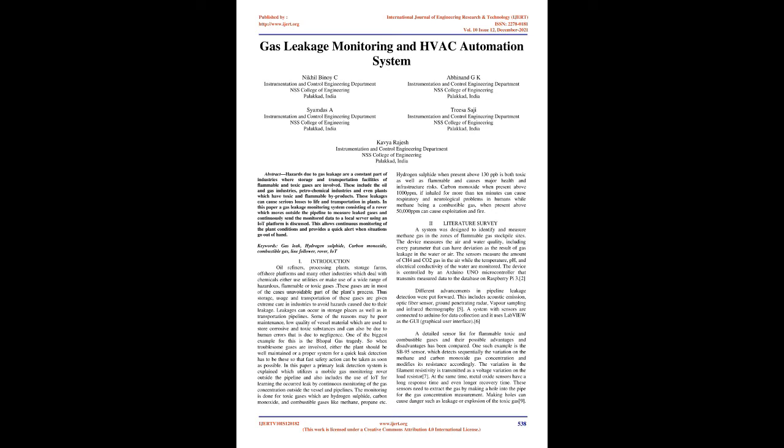Carbon monoxide when present above 1000 ppm, if inhaled for more than 10 minutes, can cause respiratory and neurological problems in humans, while methane, being a combustible gas, when present above 50,000 ppm, can cause explosion and fire.